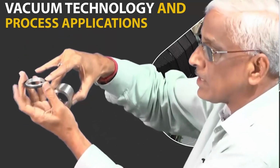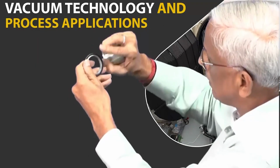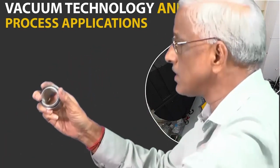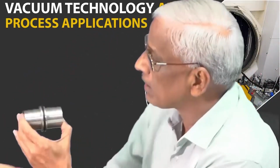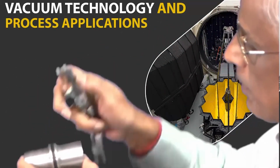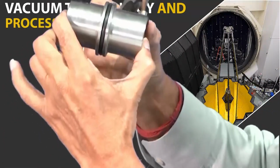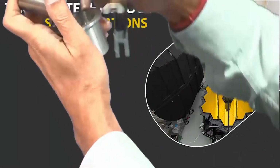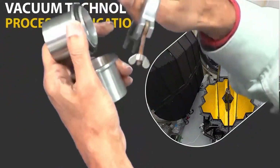because this extra protrusion will go into this slot and the O-ring portion touches this, and next section the other mating flange will come here. Then you put a coupling, and these are 15 degrees, so that when you apply force here, a part of the component goes here with a smooth pressurizing like this, so that the small roughness that may be there in micron level gets compensated by this O-ring.